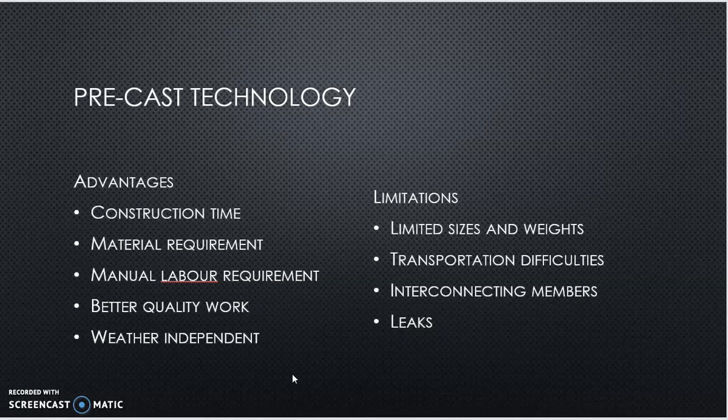This entire methodology becomes a little more weather independent. Otherwise, if you are casting something on the site, say a slab, the moment it starts raining, you will have to stop the work. But this doesn't happen if you are going to use precast slab panels or hollow panels, or precast joists. Then you don't have to wait for rains to subside. You can go ahead with your work. All you need is to get the panels and place them in position.